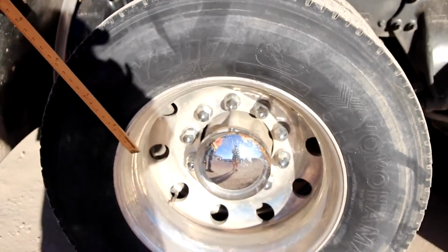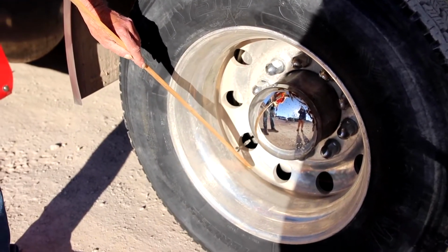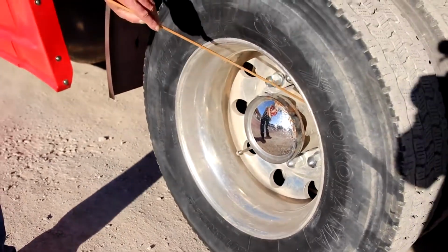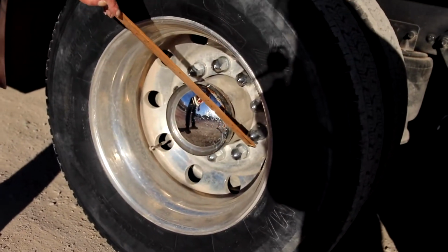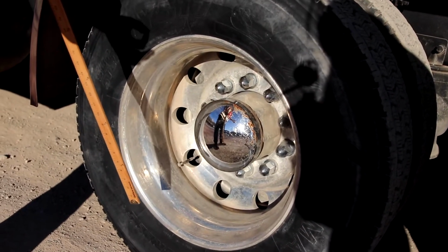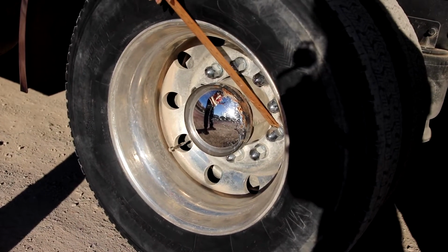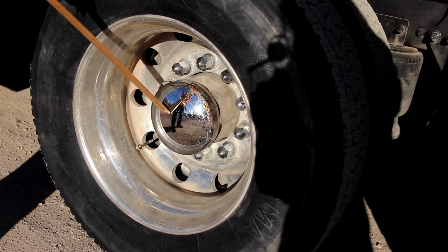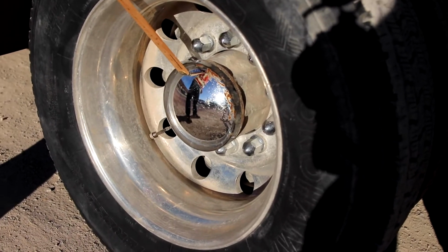To the outside of the rim, no damage, no illegal welds, mounted securely to the vehicle. My lug nuts are all present, mounted securely to the vehicle. Again, no rust stains to indicate that they are loose. And if you pull off the decorative caps, there should be no shininess on the lug to indicate that they are over torqued. Behind this cap is an axle seal.